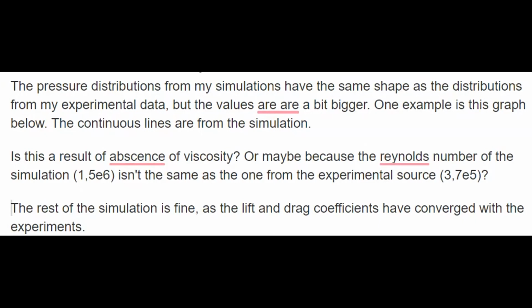If we are talking about a difference of maybe 5%, then the viscosity can explain the problem. If we are talking about 20-30% different pressure, viscosity will not consume so much energy, and the pressure will not drop 20-30%.